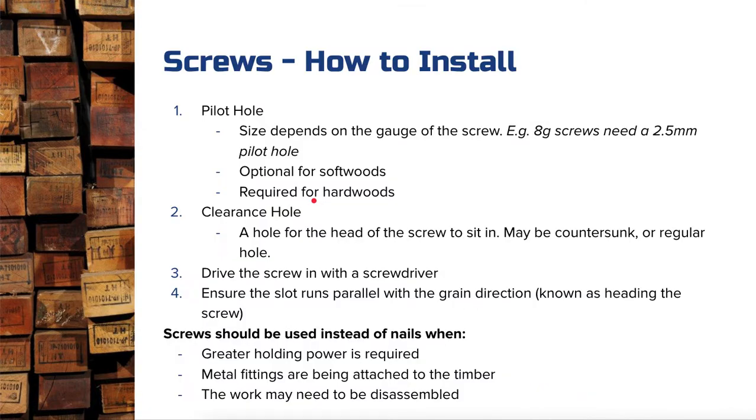How we do that, there's a bit of description there. You can pause this and go back to it. But the one thing that I'll point out here is the G number, 8G. 8G screws are the ones that we're typically using in the workshop. They've got fairly good holding power there.